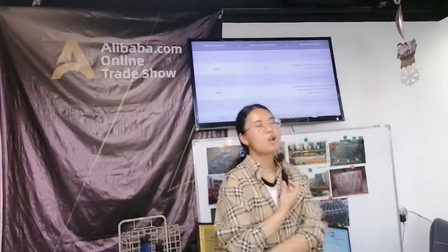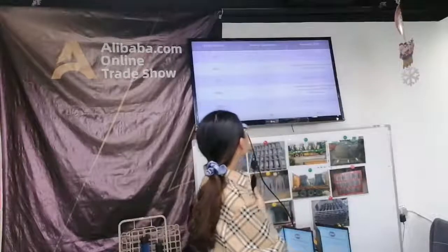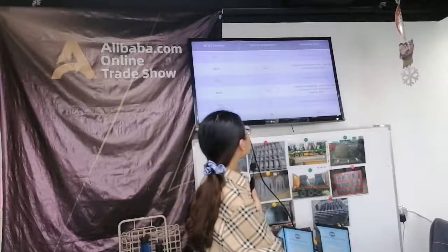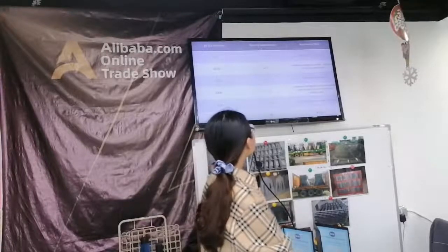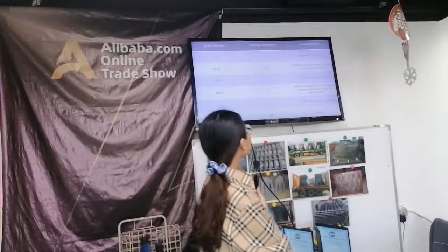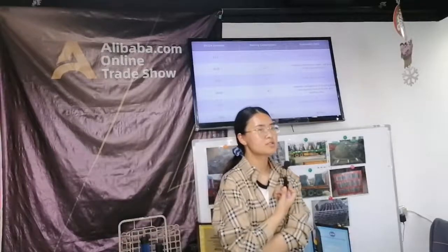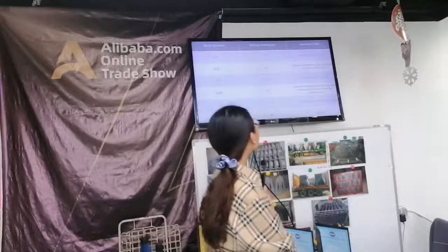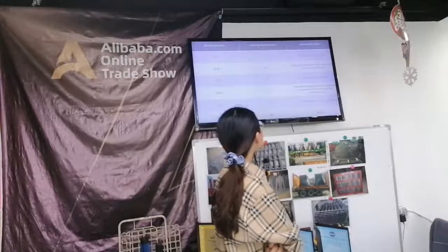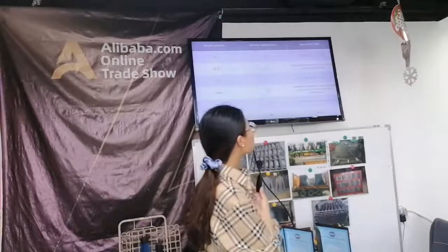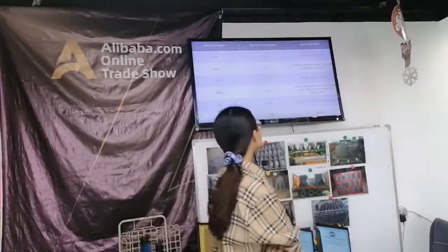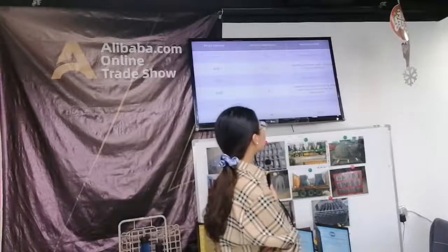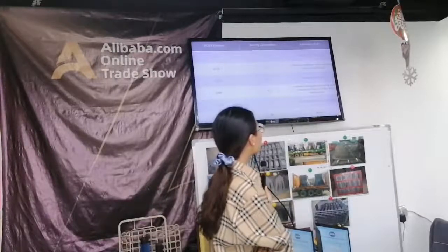As you know, our metal cover complies with the EN 124 standard. You can see the specific data on our screen. For A15, the bearing capacity is about 1.5 tons, and it is very suitable for pedestrians and bicycles. For B125, the bearing capacity is about 12.5 tons, and the application fields are footpaths, pedestrian areas, car parks, or parking platforms.